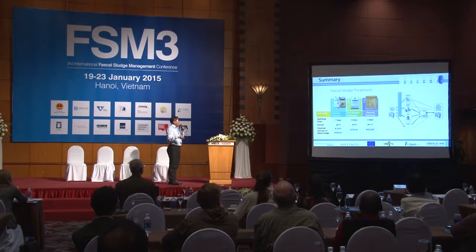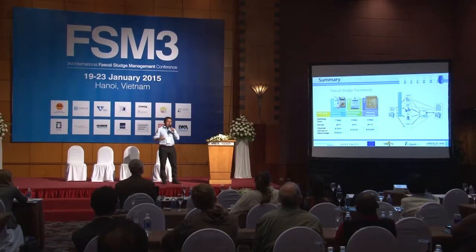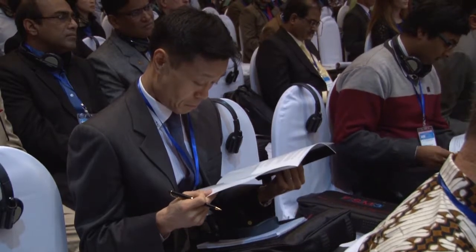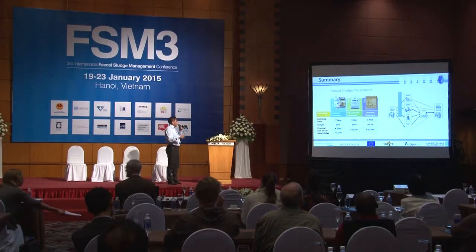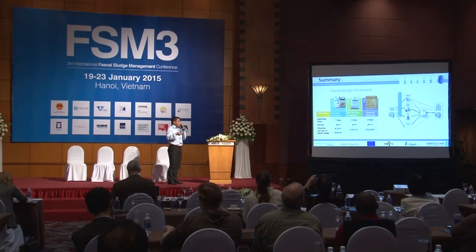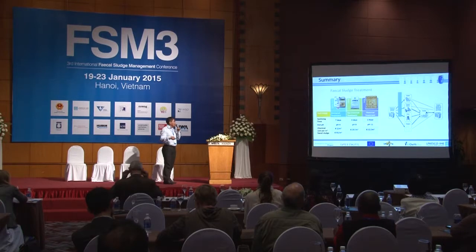The pH also is very important to mention because we have to look for some other solutions for a final disposal because the final products are very acid or very basic. As you can see, with the treatment method based on lactic acid, we have a final pH of 4, for urea pH is 9, and for lime pH is 11.